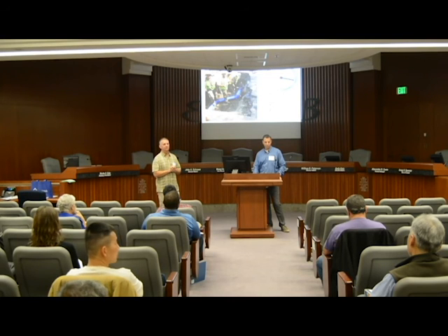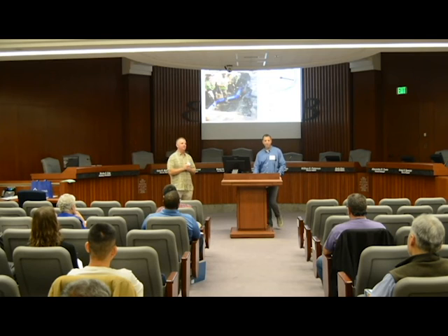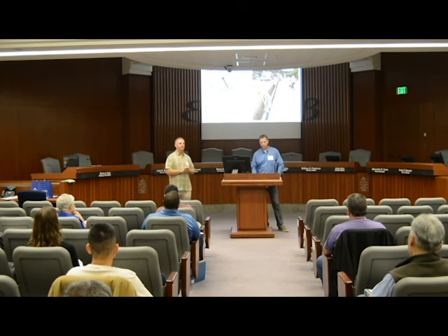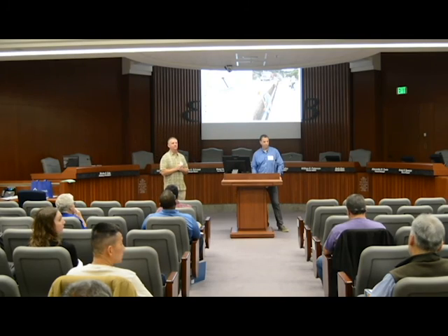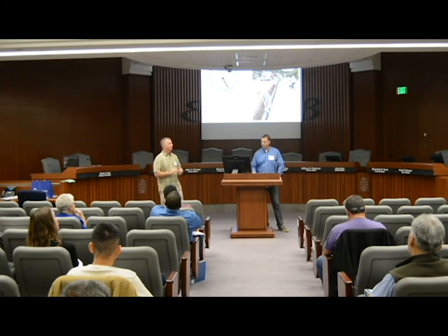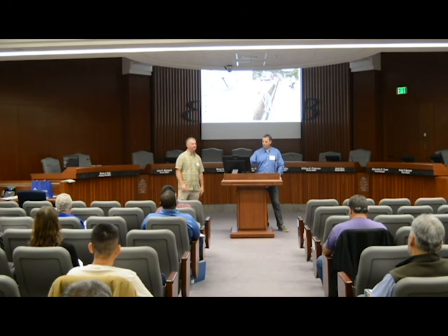What are those couplings? I've never seen them. It's called an RCT, and I can talk to you afterwards. It's a ductile iron RCT if you Google it. Basically like a self-locking fitting, you drop it in, and it's got some metal teeth that bite in. Is that for PVC? Yeah. And I'll send you a video of some tests that we saw. Appreciate that. Thank you. So I'm kind of running out of time here.